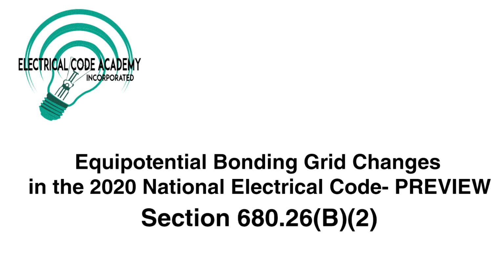So we're going to start looking at different changes to kind of give you that heads up. As the screen shows today, we're looking at a change that's taking place to the requirements for the perimeter of pools, dealing with the equipotential bonding grid or plane, as it's in section 680.26(B)(2). In this presentation, we're going to look at the change and what's to take place. The only significant change here is that we're giving you an additional method in order to create this equipotential bonding plane to get rid of those differences of potential.